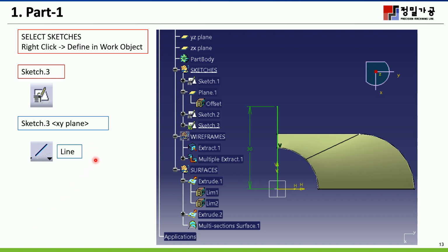And after this, we want to create the surface from the bottom. So using extrude also, just create a new sketch in the bottom on the XY plane. Using the line, in this case I put geometry dimension 30. I think it doesn't matter. You can use 25. I think you must go upper limit from this one. Okay,